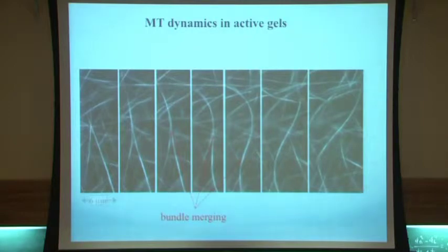But now they are in a gel, so if a single filament bundle extends, it can just simply extend. But since they're clamped at the ends, what's going to happen is that they're going to buckle at a certain wavelength. I think that's the main wavelength that determines the behavior of the system. So you can see this point over here grows and buckles, and at some point the curvature becomes so large that the thing fragments into pieces.